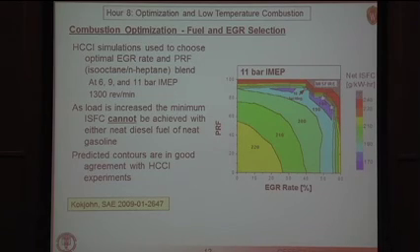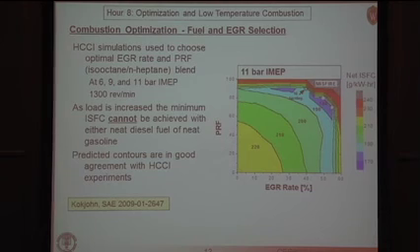Okay, so HCCI, as I mentioned to you before, is limited to light loads. And if you look at these pressure rise rates, they're actually very, very high, and really would not be practical. So the thought was, could we somehow get this effective plot here, but with lower pressure rise rates, by instead of pre-mixing the two fuels to create a certain PRF, in other words, pre-mixing diesel and gasoline, could we do it by separately injecting the fuels and doing the mixing in cylinder?